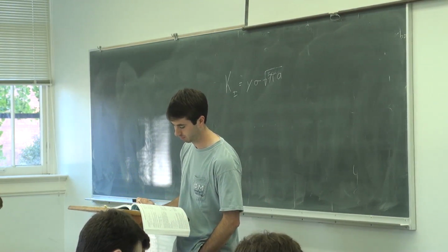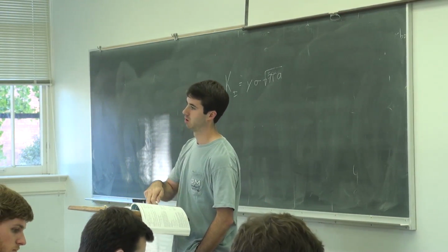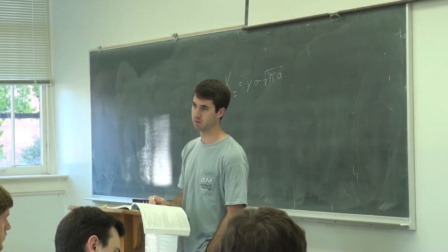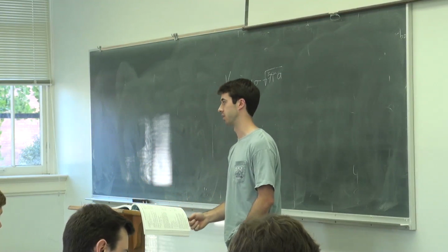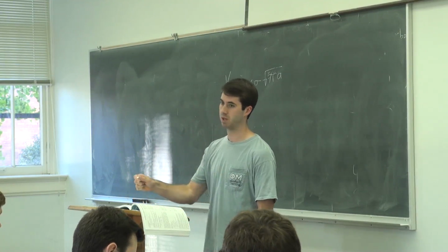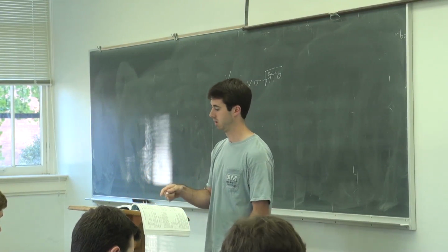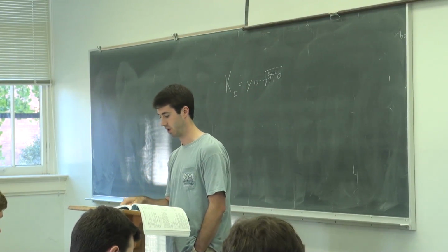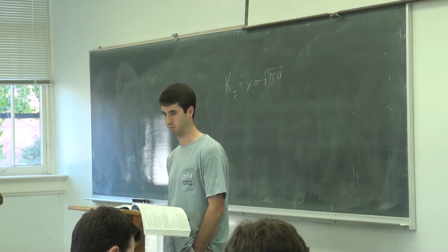What are the units of the K_I value? MPa times square root meter. Yeah, and we're given millimeters. So little things like that, if you're flying through that test and you think I've got 2 minutes to answer this problem, you'll blow right past that and get it wrong, because more than likely they've got an answer there that would be the answer if you calculated it with 4 instead of 0.004.